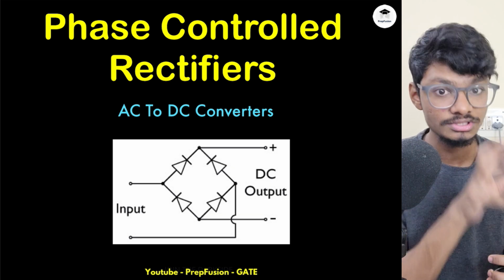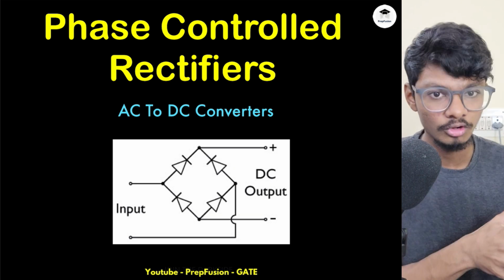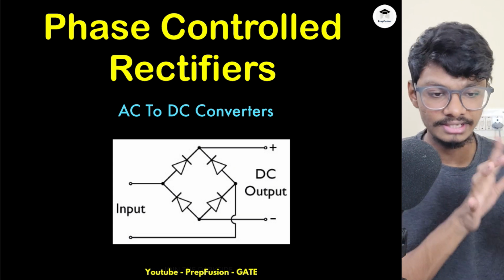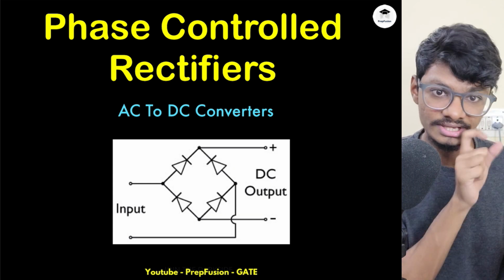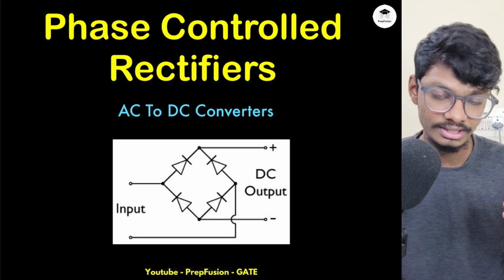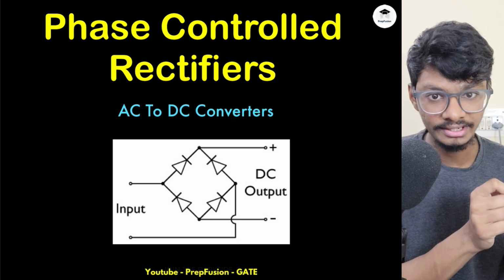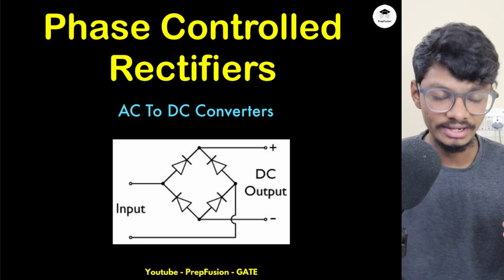There I have mainly used diode as the switch. Here I will use SCRs as the switch, and obviously diode will also be there, but mainly we will talk about SCRs, and just take some conditions for which the SCR will be used as a diode, because SCR and diode are the same, but SCR has just a firing angle where it can turn on. It can block forward voltages as well, while a diode cannot.